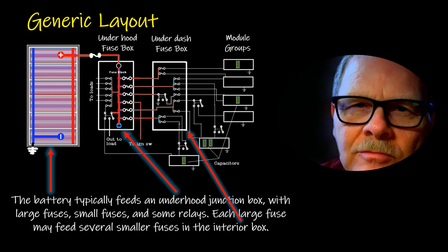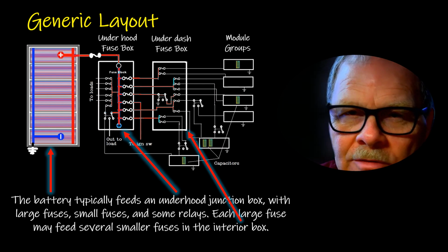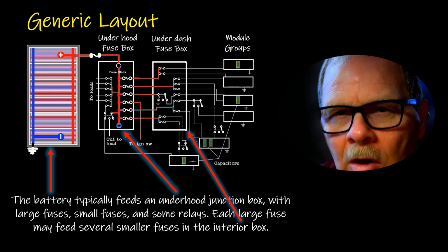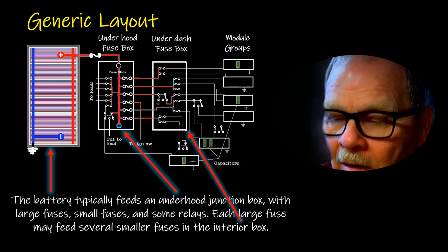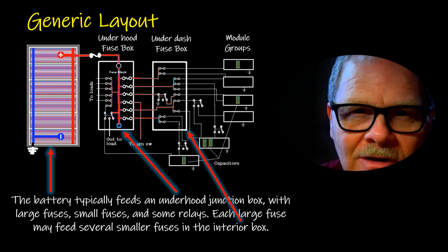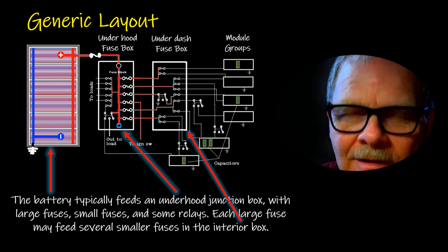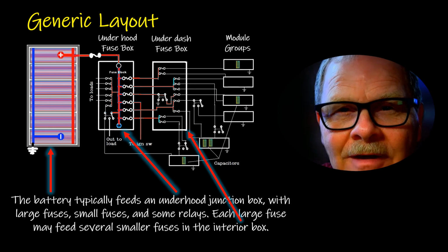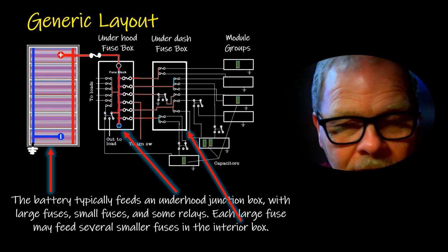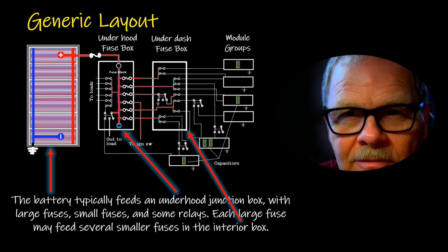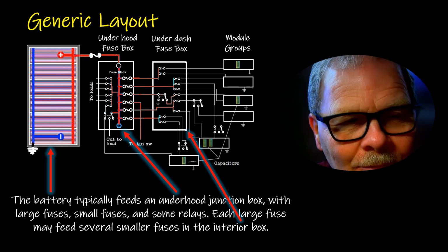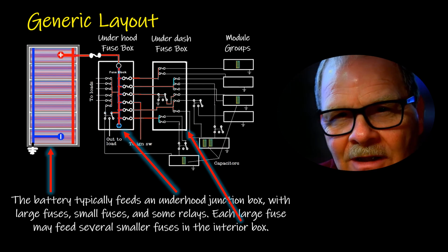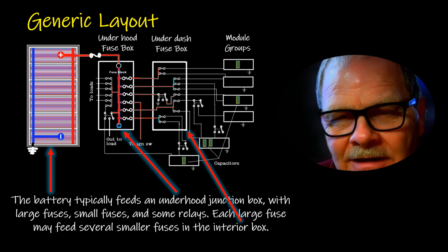Typically, the underhood fuse box will have some larger fuses. It'll have smaller ones too. But whenever you find which small fuses the large fuses are pulling, I start by pulling these big fuses, the maxi fuses, while watching my current. Sometimes I'll use an oscilloscope with a little inductive current trace going on the screen, and when you got a draw, it'll be above zero, if you zero your probe before you put it around the wire. And so whenever you pull out the one that zeroes it out, the scope will tell you exactly how much is being pulled by each load.